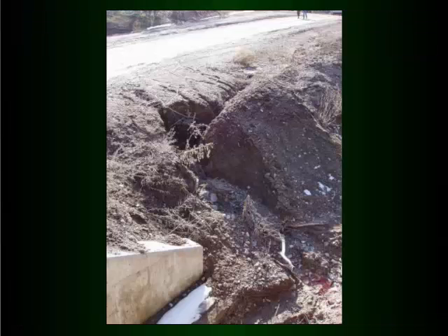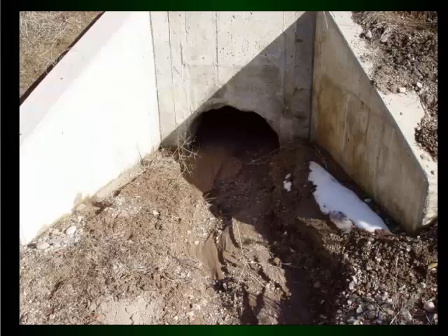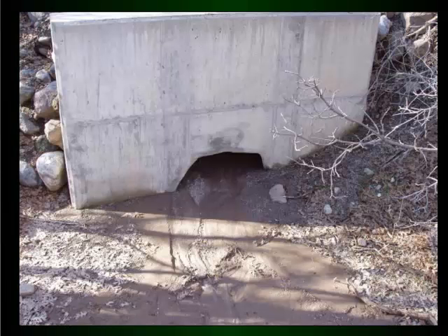This is one we'll stop at, so I don't have to say too much about it, except you can see a lot of this material is deposited here. It's actually from this cutting action, and this feeds into, I think, a 30-inch pipe right there. This is the 30-inch pipe. This sediment, once again, isn't from the stream itself. It's just from adjacent ditch water being dumped into it. At this end, it's about 40% filled up. At the other end, it looks like it's about 60% filled up.